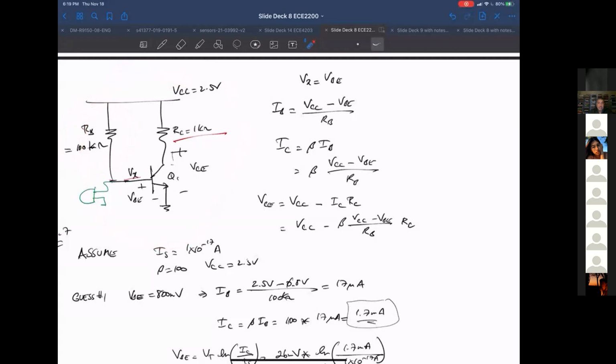So you need circuits that don't break if the beta of your device changes, because it's guaranteed to change very much. What's even worse, or maybe the same, to further talk about what can go wrong here, is that I was showing a graph in that data sheet that even for the same device, the beta changes by maybe a factor of 50%